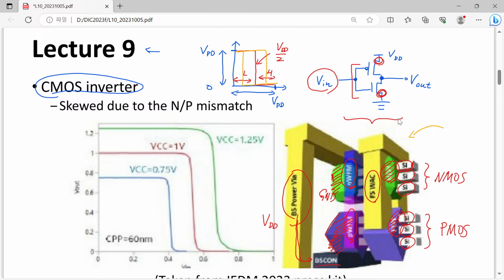So usually up to now we must draw NMOSFET and PMOSFET separately in our layout, but in this new technology we can just overlap them all. Then roughly speaking, we can reduce the consumed area by a factor of 2, because previously there were 2 separate MOSFETs, NMOSFET and PMOSFET, and they are overlapped now.